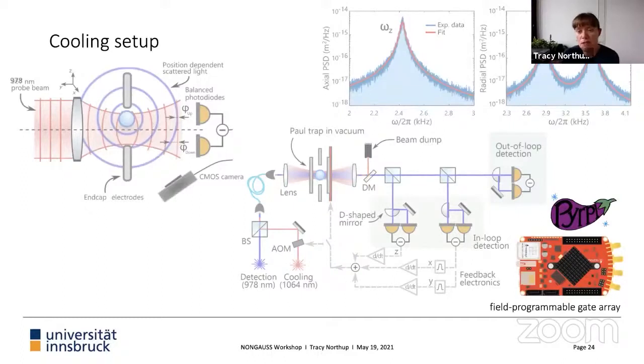And then we're using feedback here. This is with a Red Pitaya and using open source PyRPL software. So we're taking information about the particle's position, and we're essentially just taking the derivative of that with this FPGA system. And now we have a feedback signal that's just pushing us back based on the derivative of the positions. That's giving us the velocity. And we're summing those signals back together because they're at different frequencies. And now we do 2 things with that feedback. We either use optical feedback or we use electronic feedback.